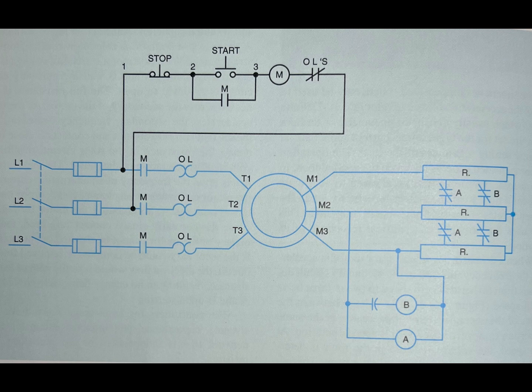Frequency relays have a number of advantages, including positive response. Operating current drops sharply as the frequency drops below the point of resonance. Accuracy is maintained because this type of relay operates in a resonant circuit. Simple circuit. Changes in temperature and variations in line voltage do not affect the relay. An increase in motor load prolongs the starting time.